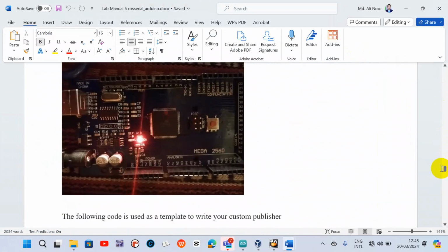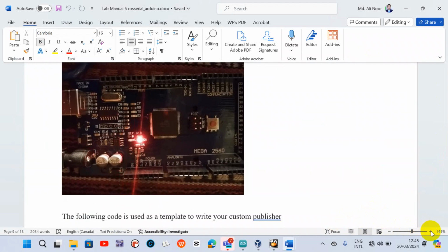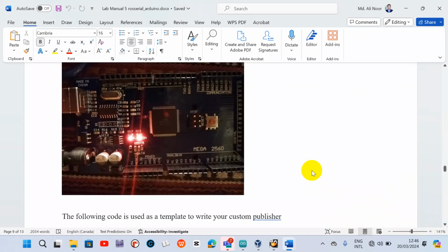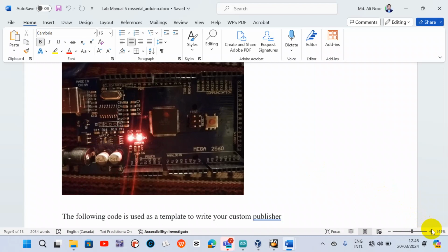You see, the LED is toggling over here. Modify the rostopic pub command on your ROS so that the LED will blink at a particular rate. Do a search on Google on how to modify the command. Okay, so that's your lab. If you have any question, we can go through it now.